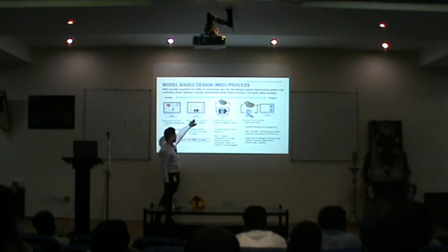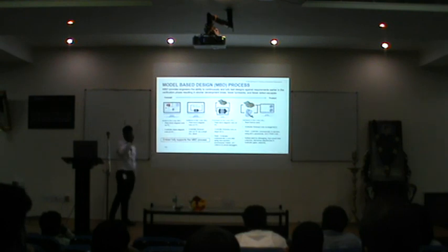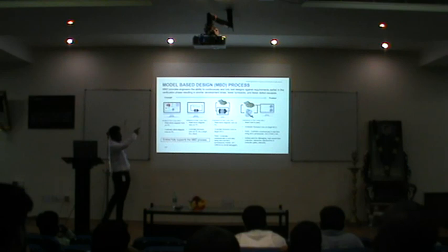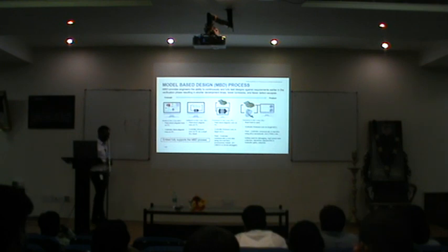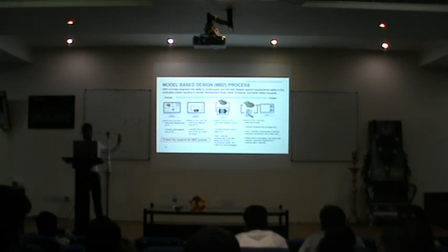When it comes to PIL, the plant model will be virtual, but the controller will be running for real on the microcontroller target. That is PIL. And then HIL is nothing but the real motor, the real inverter and converters. I'm going to show that. I bought small motors to show you the closed loop FOC algorithms. I'll show you how HIL works. So this is a process that goes from concept to end design.